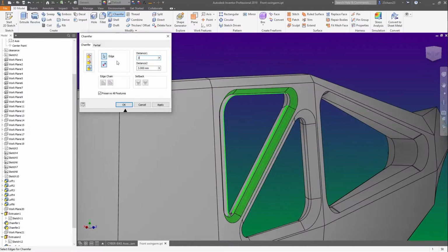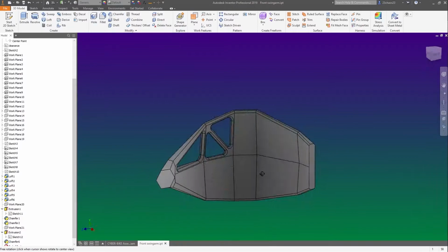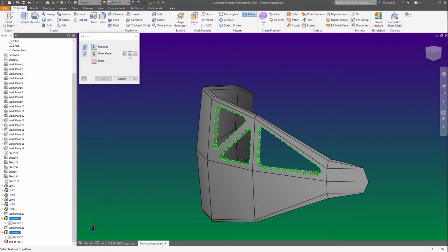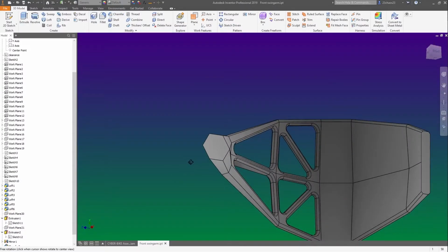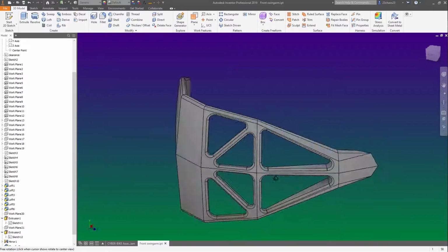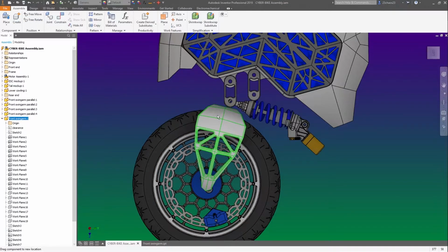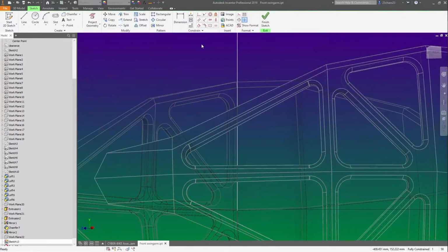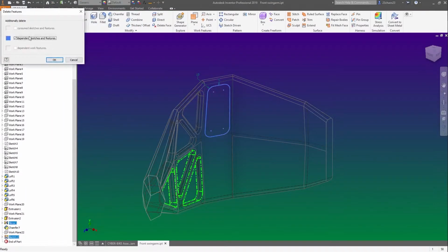And I didn't stop here. I thought, okay, well, let's just keep adding these cutouts all the way through and keep the look of it uniform. That just wouldn't work. I ended up doing the stress analysis for it, and it just kept twisting no matter what I tried. I tried changing the thickness, the minimum cross section of those cutout sections and stuff like that, and the simulation just kept twisting it out. So I was like, you know what, bugger this. I'm done with trying to do this aesthetic stuff myself. We're going to let math sort it out.